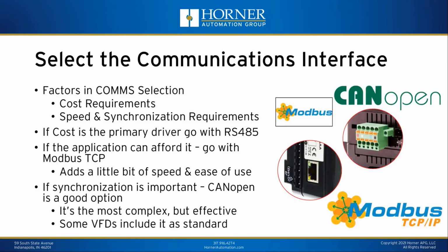All right, so we've done a little bit of hardwiring in most applications. Again, not absolutely necessary. The next step is typically to select the communications interface. And in reality, there's no absolute ironclad requirement that you connect a communications interface between the drive and the OCS. You could strictly use I/O connections. Now, if you do that, you're going to be limited to strictly start, stop, speed control, those sorts of things. You're not going to have access to any kind of diagnostics or real-time data, those sorts of things outside of what you've hardwired. So we typically do recommend that you go ahead and connect the network.